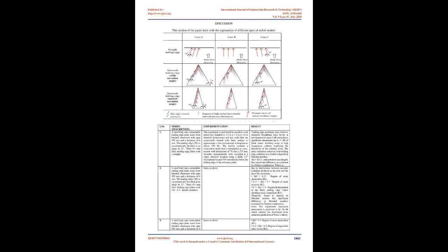It is shown that trailing edge noise could be effectively reduced with the use of a serrated trailing edge, and the magnitude and frequency range of airfoil trailing edge noise reduction change with the increase of main flow velocity. In the frequency range of 10 kHz, the largest noise reduction of sound pressure level is about 5 dB with the use of a serrated trailing edge in the test flow speed range. The predicted results of Howe's theoretical model are in good agreement with the experimental results.